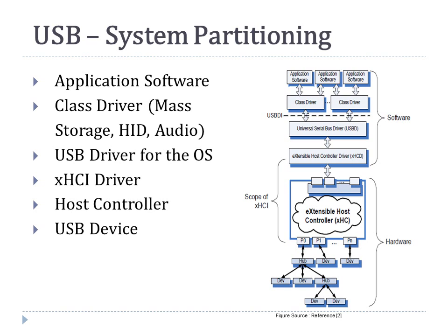And more on the system partitioning, most of the physical layer, which is the port and its functionality and the controller, is in the hardware. And then we have the software stack, which comprises the host controller device driver. This basically abstracts the hardware to the OS. The OS doesn't need to know which controller is implemented, and it uses a very similar interface for doing the USB functions.